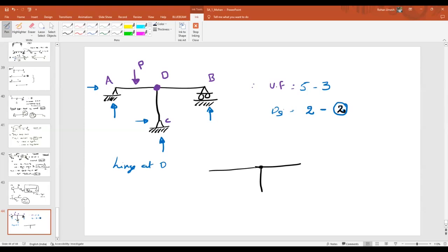This is not a hinge. I'm just concentrating here, okay? Don't treat it as a hinge. A, B, C. I want to draw the free body diagram of AD, BC, and DC. Let me represent the moment here. In the member AD, can I represent it as MDA? What does it mean? Moment at point D towards the direction A.